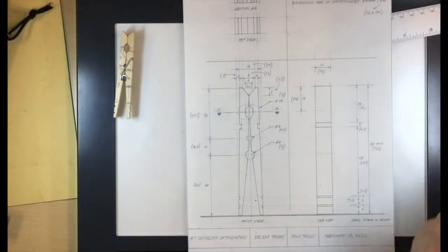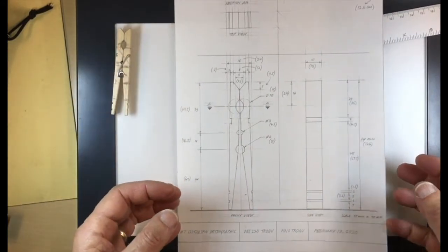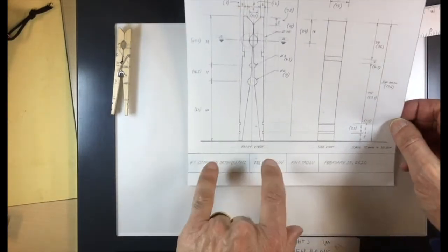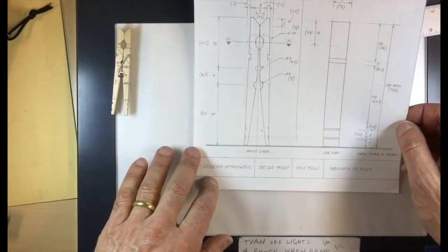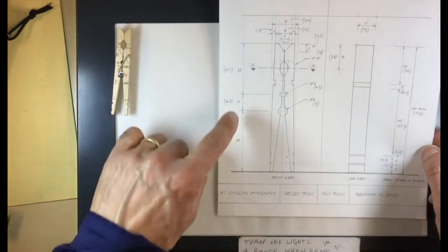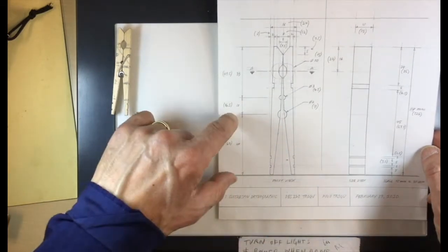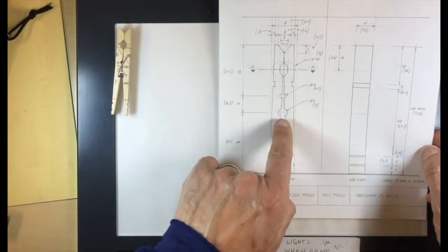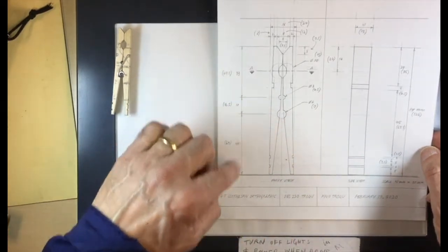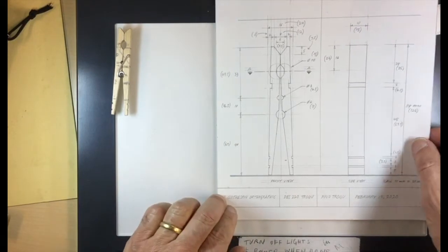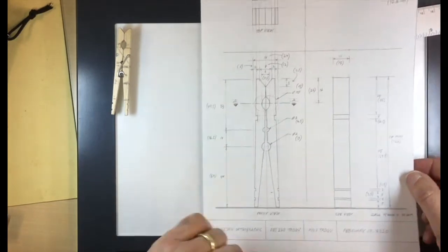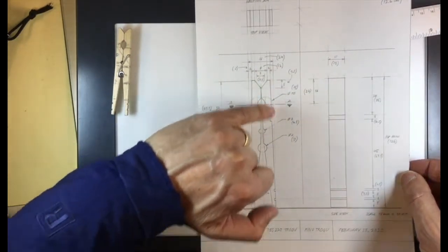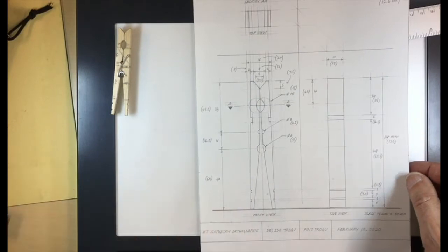But we're not there yet. So the other things are that, as a convention, I did a double line to show the ground line. It's just a technique we did when I went to school. And then we're going to add some dimensions, which are lines with numbers, showing from where to where, how big things are, okay? And these are little arrows in a particular shape to indicate that. And then we're going to indicate the radiuses of the circles. And yeah, that's it.